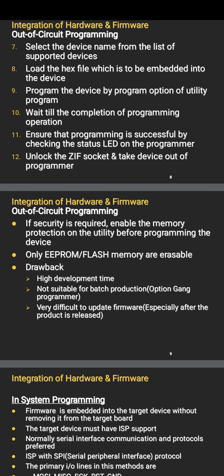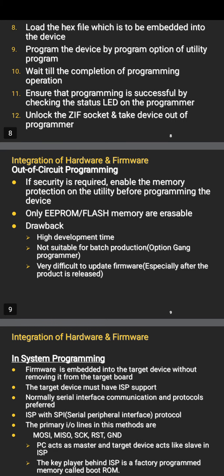Next, there are some disadvantages of this system. First is the high development time. It requires high development time. And the second disadvantage is that if there is any change in the firmware, the only option is that the chip needs to be taken out of the board for programming. And when we are frequently removing the chip, there is a chance of chip damage. And here at a time only one chip can be programmed.